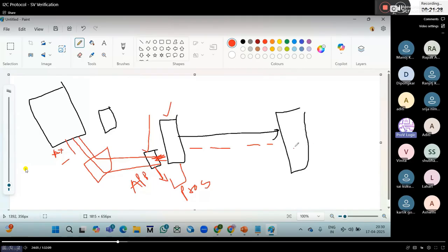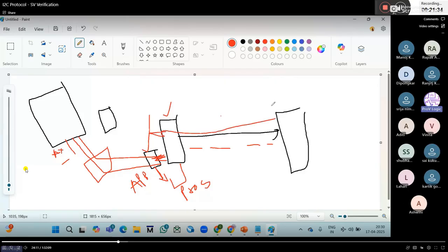The slave can send to another master. It may be the same master sometimes, or some other device. Suppose this slave is communicating with a memory controller. The memory controller will accept only parallel data because mostly we use the APB protocol here. So to convert this serial data to parallel, we use SIPO, a serial to parallel converter.